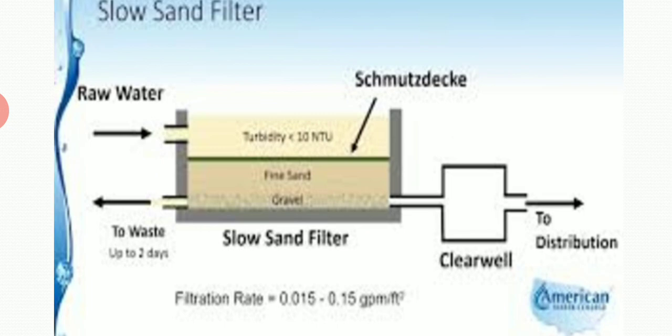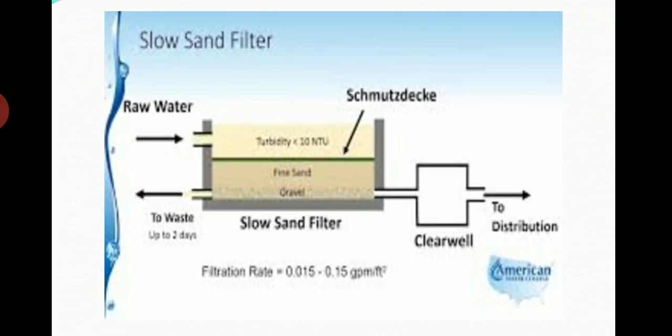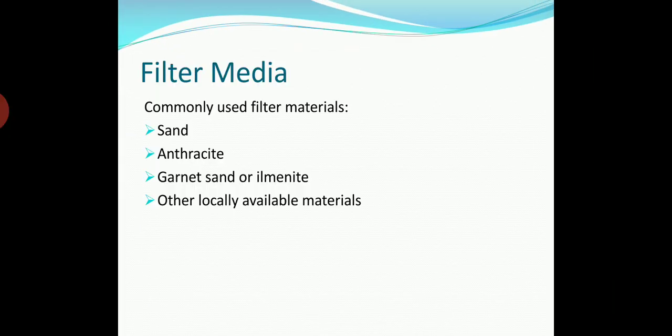So all these four things are important, that is mechanical straining, biological action, sedimentation and electrolytic action. If they go hand in hand, we have good filtered water coming out from the other side. So this is the mechanism of filtration.